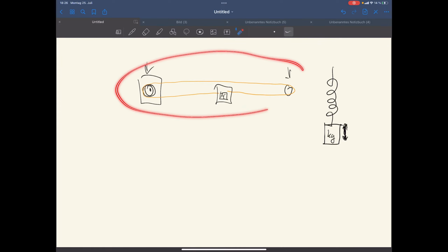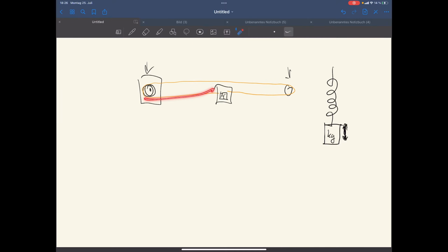So for a printer designed like this, which is a Cartesian printer, we have ideally one resonance frequency per axis, which is defined by the length of the belt and the weight which is attached to it. Namely the printhead or the print bed on a Cartesian.